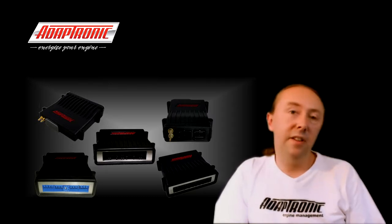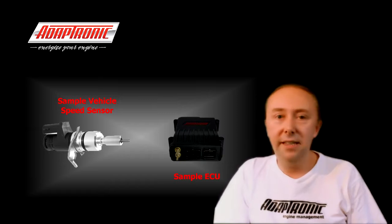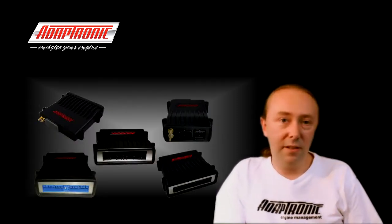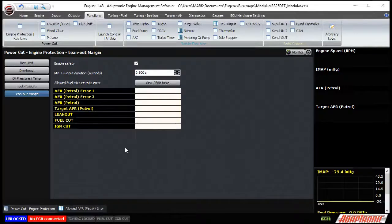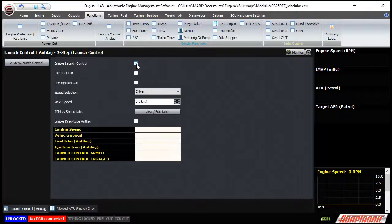Now to use this function, you'll need to have a vehicle speed sensor hooked up to the ECU, so that the ECU knows when to start applying the function and when it's out of the hole so it can stop and revert to the full power potential. To enable this, you need to go to the functions, launch control / anti-lag, and then go into the main screen of that and then select enable. That will allow you to see the settings and enable the function.